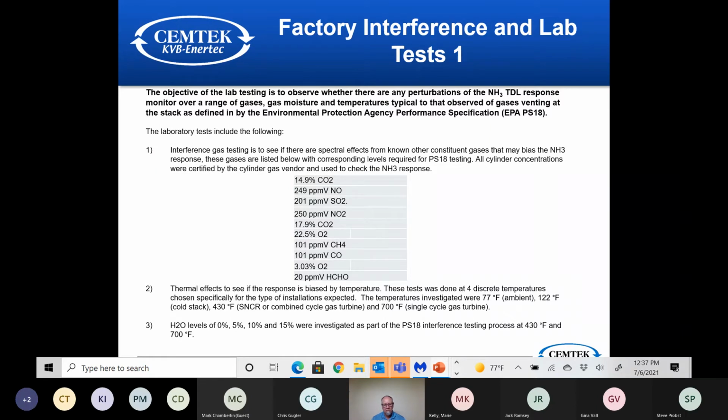And then because we're fiber optically coupled, as I said earlier, if you're not doing this for compliance and you want to measure ammonia slip at the duct and you've got 2 turbines side by side, or 2 units side by side, we can split the fiber optics, send it out to each one with 1 instrument, and you can lower your overall cost. And we can do up to 8 instruments. It slows your response time down when you do 8, but we have many where we're doing 4 and 6 that we've been operating for 15 years very successfully, almost no downtime at all. Just clean the lenses quarterly. Somebody goes there and cleans the optics. That's it.